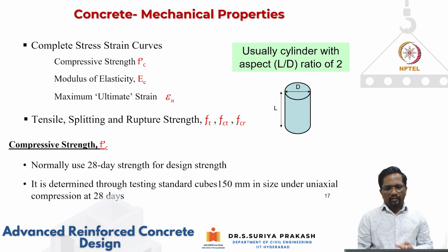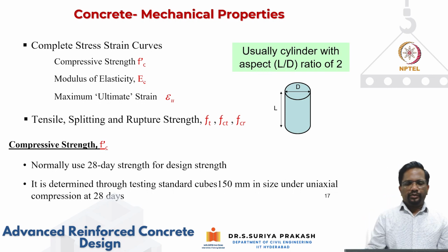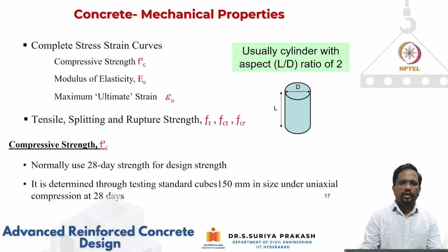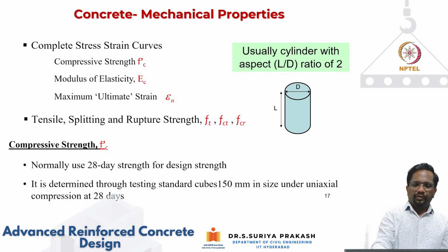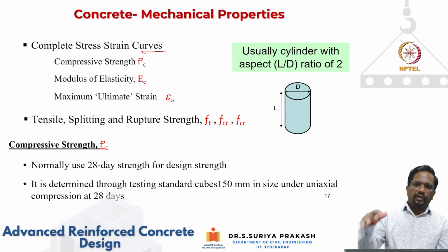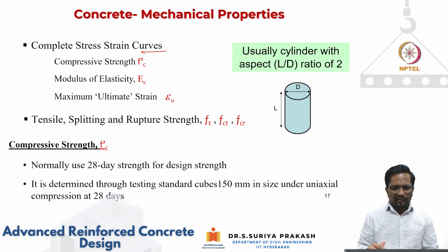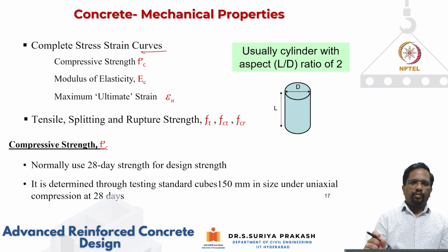Right. Now let's get into the mechanical properties. As structural engineers, we are usually more concerned about how the sustained behavior of concrete is going to be under compression, tension, and so on. We want these properties to be used for design. Ideally for a design, we need to get complete stress-strain curves. But for every project, we cannot go ahead and test and develop these stress-strain curves. So people have already done a lot of testing, and they give you some simplified formulas based on certain minimum values. One of the values is basically compressive strength.